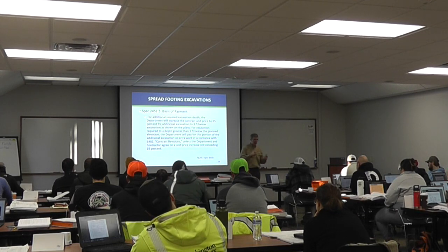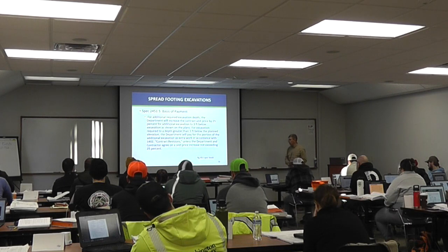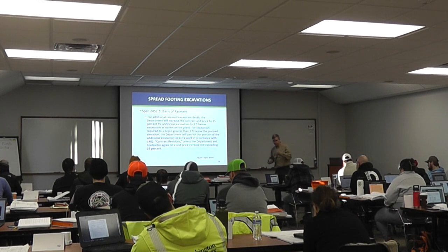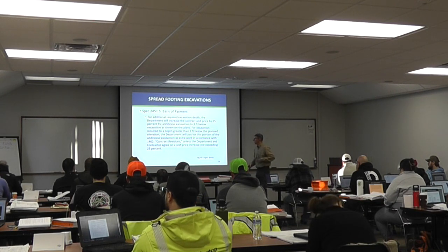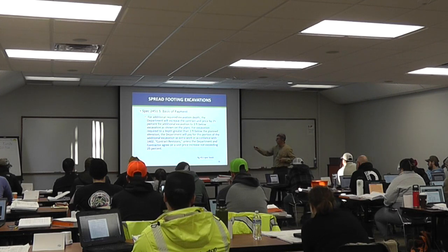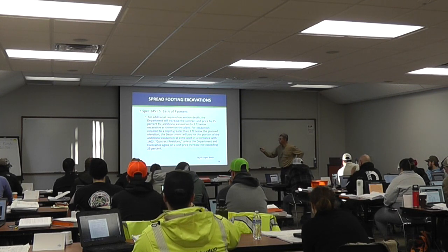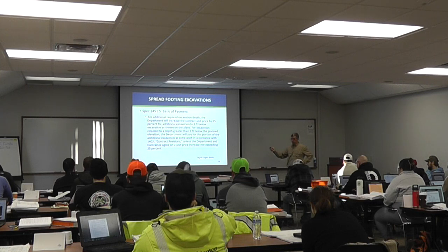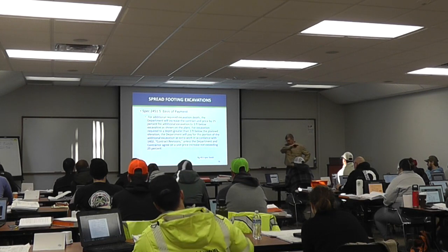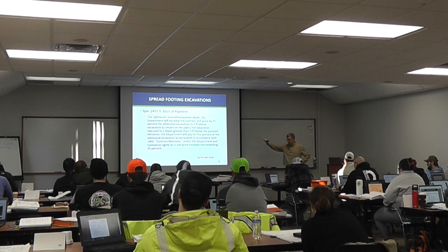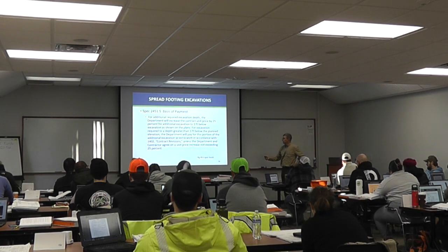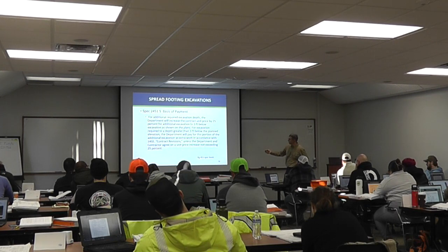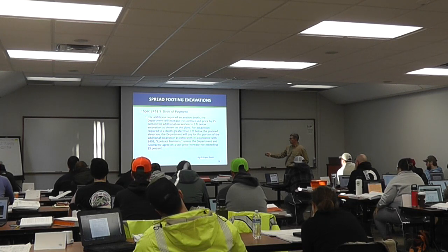So every single spec is going to be that way. So if you're ever looking for that, and where is that in the spec? That's what that payment system is. So for this one, basis of payment, for additional required excavation depth. So we say excavate to elevation and put your footing at elevation 900, and there's some unsound stuff that they end up taking out. So it says the department will increase contract unit price by 25% for additional excavation of 3 feet below excavation.